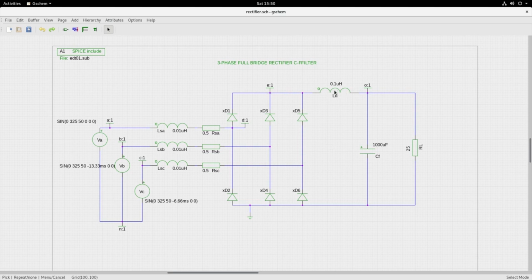So now let us see how we go about simulating, and let us see the various waveforms. We'd like to see the current at this point, would like to see this voltage, like to see all these three voltages. So let us modify the rectifier.cir circuit so that automatically it calls ngSpice, runs, and then plots the first draft waveforms.